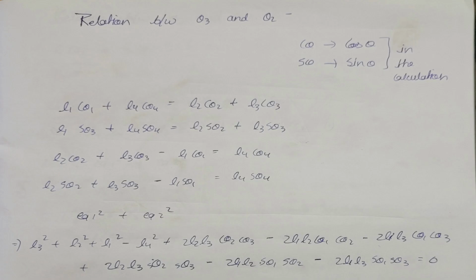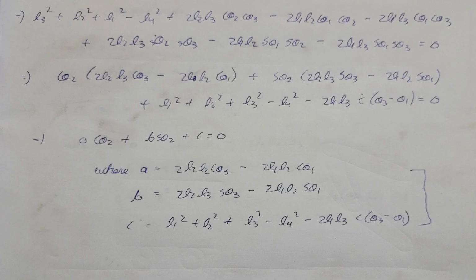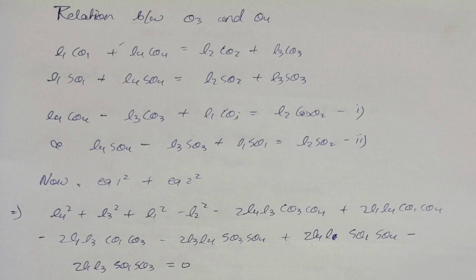Now let's look at the displacement analysis of the problem. Displacement analysis is the geometric relationship between the actuated joints and the output link without regard to the force and torques that cause the movement. We can see the relation between different angles so as to obtain the particular motion of the output link with the movement of the input link.